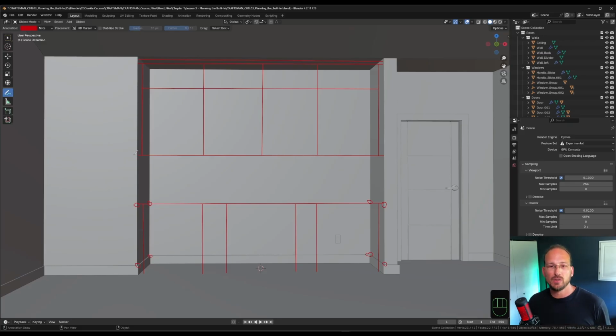And then for the hanger cabinets, we'll do the same thing. We go on the bottom, front and back, and on the top, front and back. And because these are fairly high, I would also opt to make one in the middle. And then for the height, we're going to do practically the same thing, even though we have room to play with because they're not completely connected, but still, we need to know how high the actual ceiling is. So we're going to take a measurement here and in the back. And same on the other side.